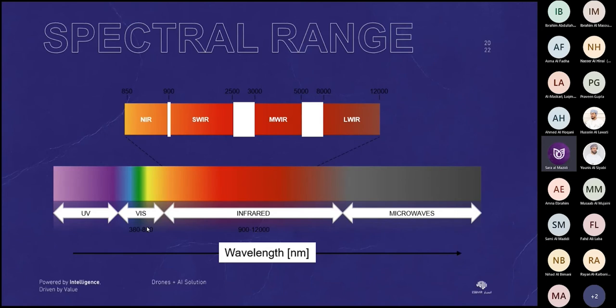The other thing I want to speak about is the spectral range, or considering the spectral range when you are in the process of choosing your OGI camera. This is very important to consider because you don't want to conclude that you don't have leaks, when actually your camera is not seeing the gas you are searching for or are interested to see. So, for example, we are considering methane. We want to detect methane. So when we look at the spectral range, you will see terms like